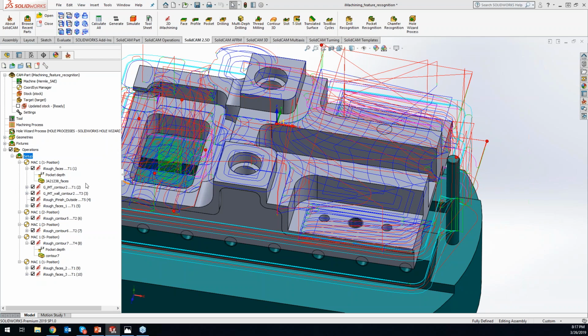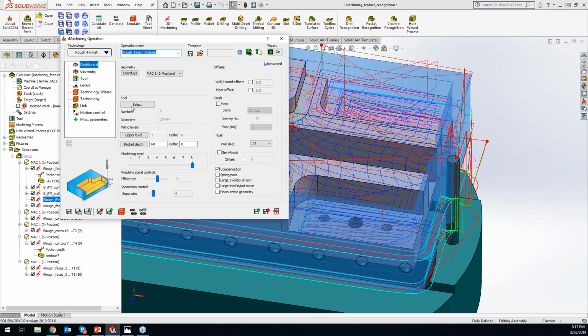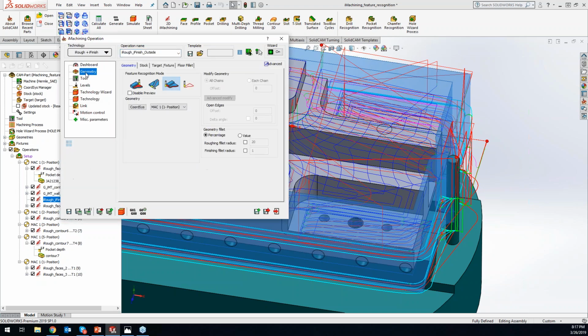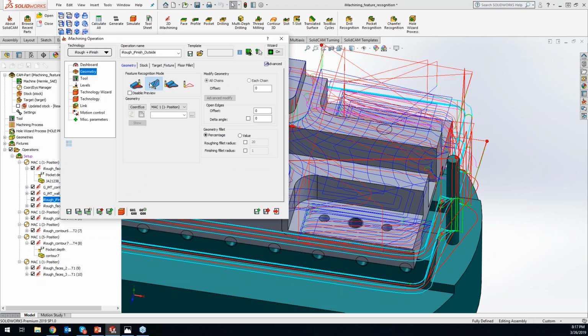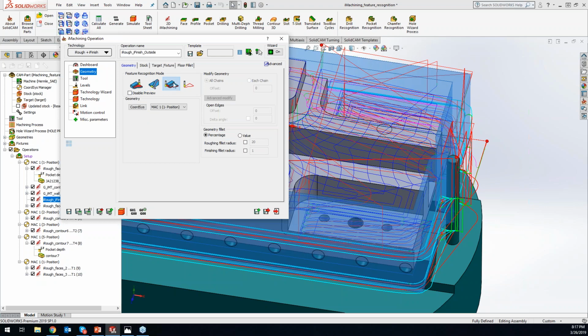But for the, let me open up the operation real quick. When you're defining it as a chain, you're saying that it can be used in any type of operation that uses a chain. Yep. So anytime we're generating a chain right here, most definitely we can. The outside perimeter is not one that can be used by any other operation other than the 2D iMachining.